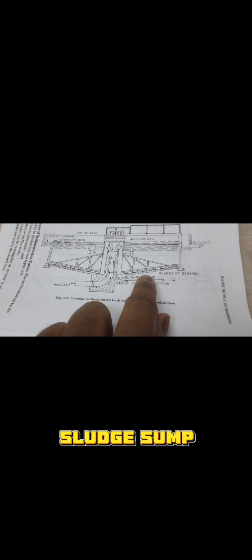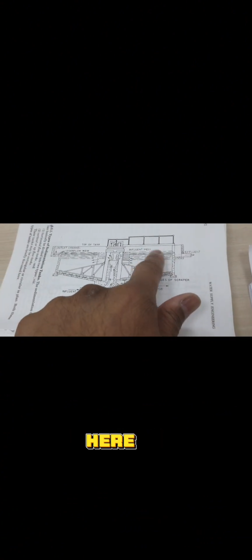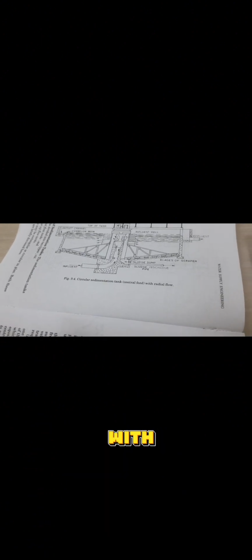This is my typical layout of the circular sedimentation tank, where you can see that we again have an inlet, and then we have the outlet channel, and also we have the weir and notches. Basically they are going to measure the flow rate of the water. Then we have the sludge pipe and sludge sump here to store the sludge, and the sludge will be coming out here, and this is the discharge, and this is my influent well. This is my whole layout of the circular sedimentation tank, which provides a central feed with a radial flow.